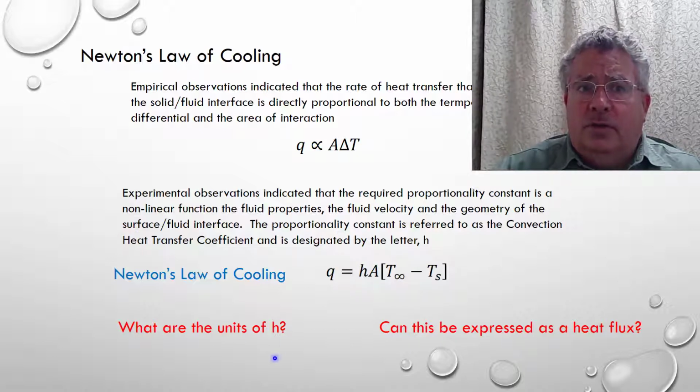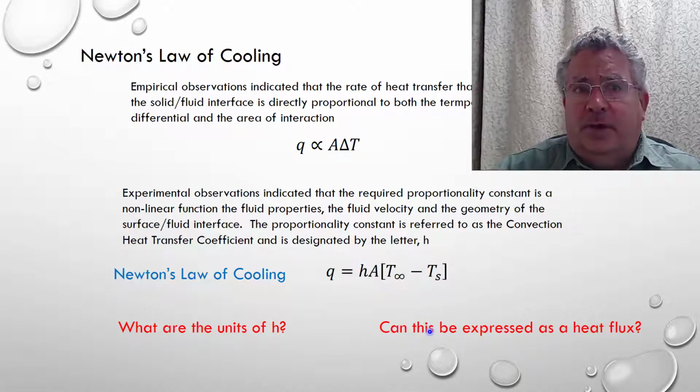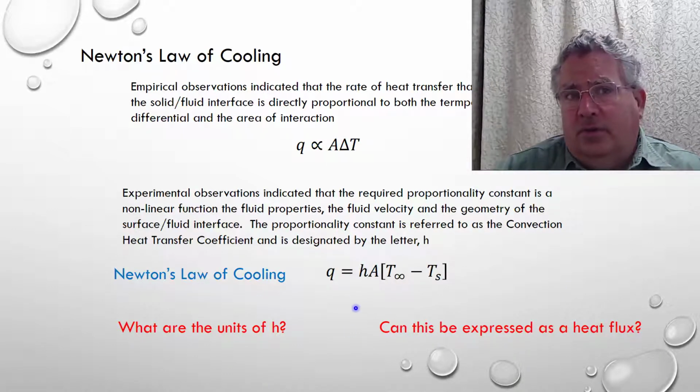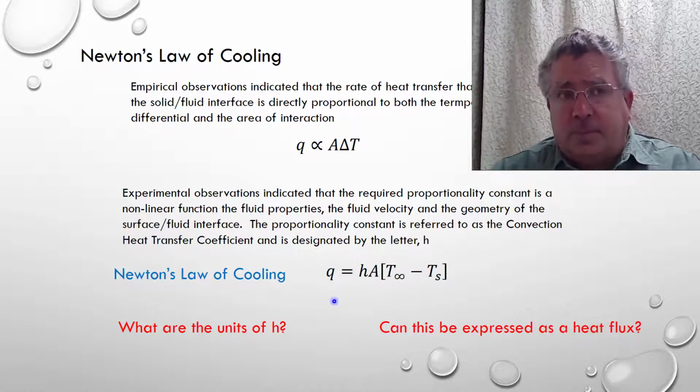Okay, so what are the units of h? Figure that out, and I say, can this be expressed as a heat flux? Well, of course it can, because we have area on this side, so I can divide both the left-hand side and the right-hand side by area, making this a heat flux.